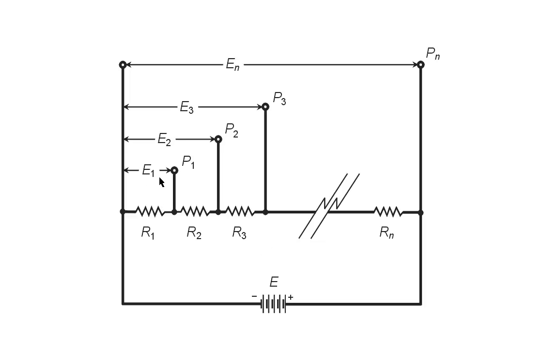Now, we need to keep in mind that this is only going to work provided that what we put across these points doesn't load the circuit down and change any one of these resistances significantly. If it does, then we're going to have a problem. Each one of these resistances, remember, is 9.0 ohms. If we put a 1,000 ohm load across here, it's not going to significantly alter the 9.0 ohms or 18 or 27 ohms. So we can put 1,000 ohm loads across here and we're okay.